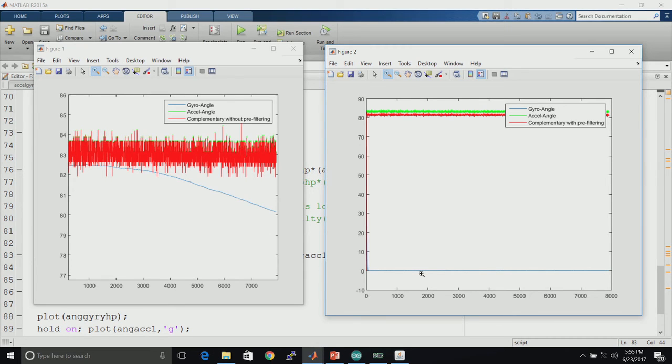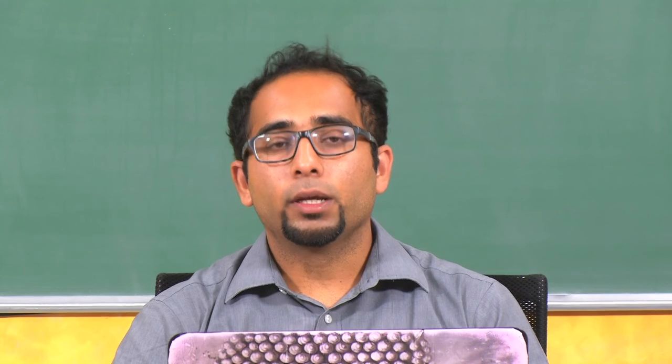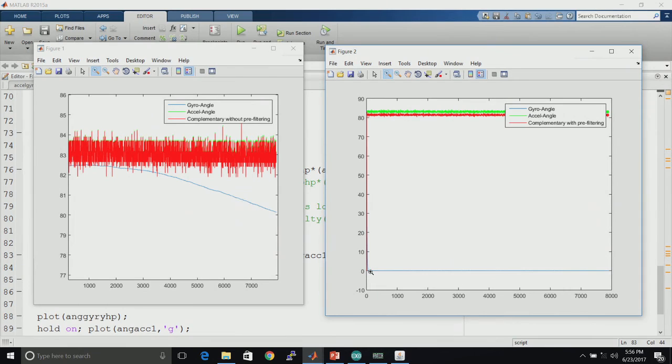So now the movement, or the angular velocity, which is present in the gyroscope is very low. So when we compute the angle, it is basically a stationary angle with lower frequency dynamics. As we see, the angles computed from the gyroscope, when passed through the high pass filter, the lower frequencies which are below the cutoff frequency are actually filtered out and attenuated. Hence we get a value close to 0, because all the frequencies present in stationary are attenuated by the high pass filter and we get a 0 angle.